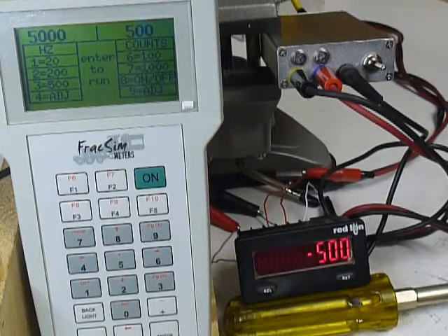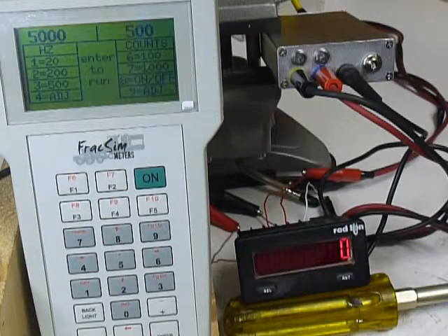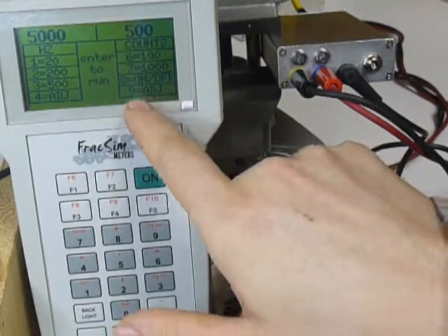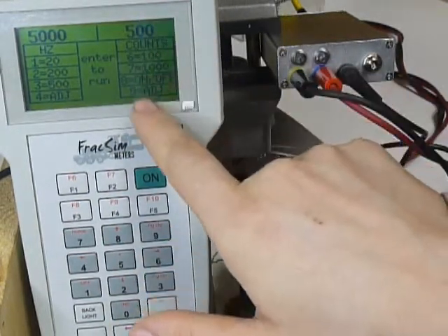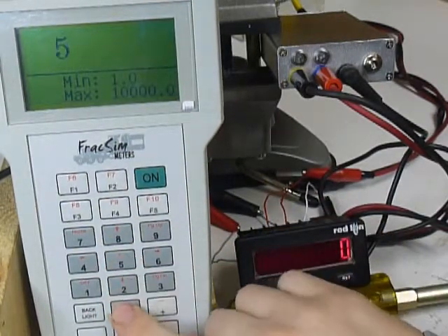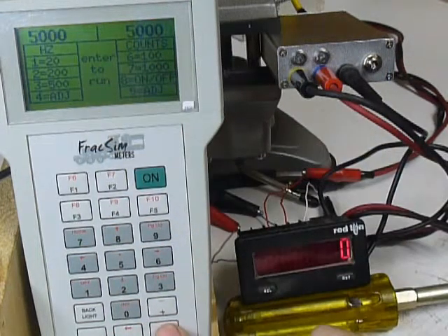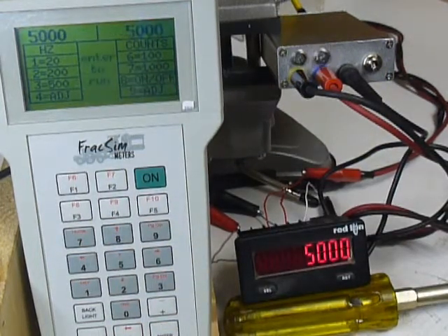Well, it looks like we didn't overspeed it. It should come up pretty quick there. Let's go the opposite direction. Let's try it for a longer number of pulses. So I'm going to go into adjust the counts over here, which is F9. So Shift F9. I'm going to put it up to 5,000 pulses. So I'm going to press enter. So it counted right up to 5,000, no problem there.